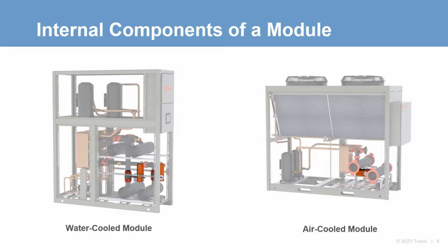Either manual or motorized isolation valves may be included as standard or as an option. This varies by manufacturer. Ensure isolation valves are available per module for service, allowing the chiller to continue to condition fluid. Motorized valves are necessary for variable primary flow systems. More to come on that later. Main point here, each module is itself a chiller.